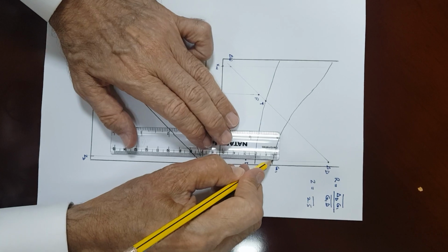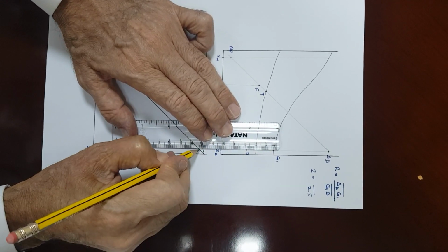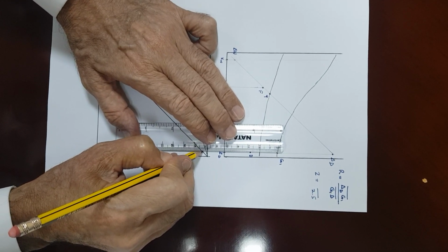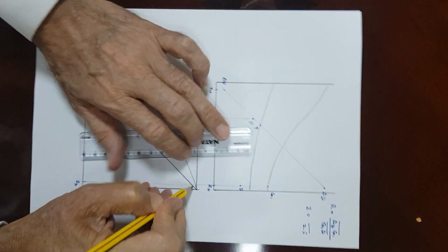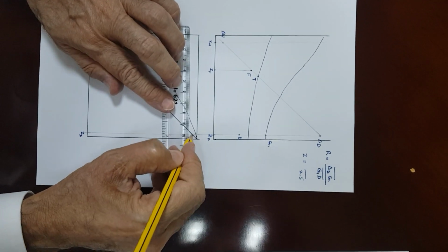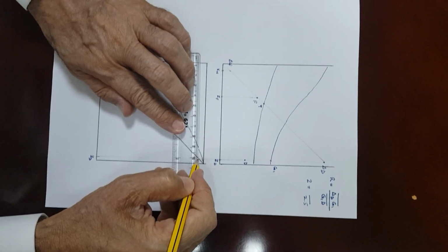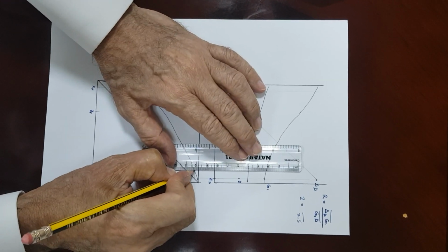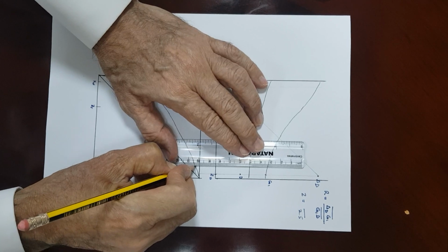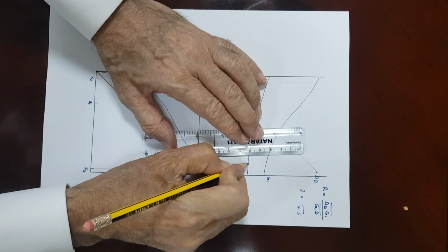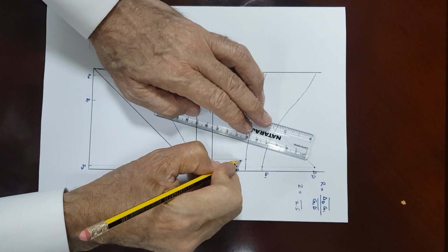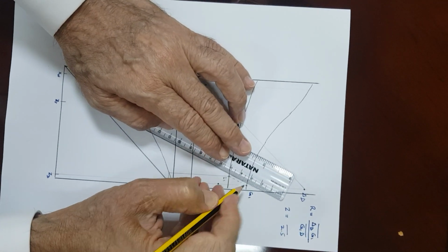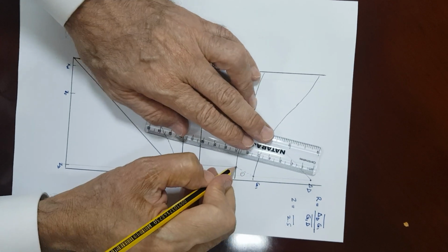So you start with G1, drop a vertical line to the 45-degree line on the y versus x diagram, then a horizontal line from the 45-degree intersection to the equilibrium curve, then a vertical line up to the liquid enthalpy. That's your L1, and you can connect G1 and L1. This will be your tie line, so that's your stage 1.